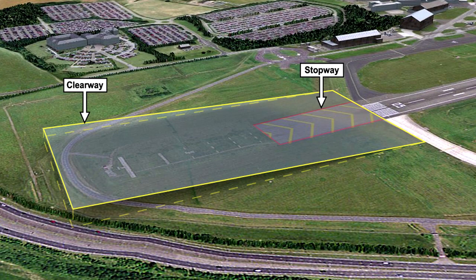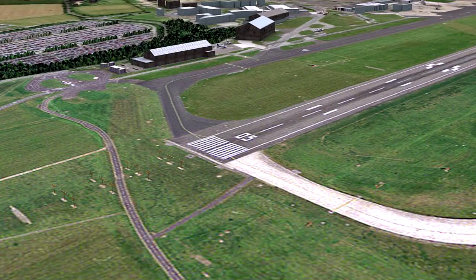Having discussed the extra runway extensions of stopways and clearways, we will now focus on three more specific distances, other than the TORA, which you will need to understand. The first of these distances is the accelerate stop distance available, or ASDA. This used to be known as the emergency distance available. The accelerate stop distance available is the distance from that point on the runway at which the aeroplane can commence its takeoff run to the nearest point in the direction of takeoff, after which the aeroplane cannot be brought to rest in an emergency without the risk of accident.